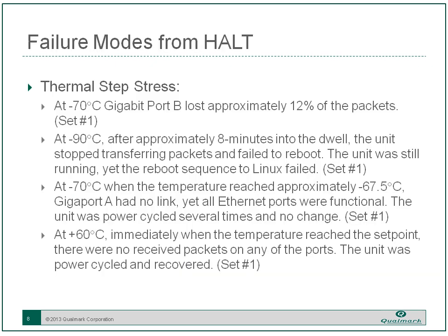Here are some examples of descriptions of failures found during a typical HALT. Simply recording just the stress level of the failure is not enough information. You'll want every detail of the failure mode to record when you move forward. You'll want to be as specific as possible, as the examples listed here are. Information pertaining to what test and specific stress the failure occurred at, how the product failed, what data functional test equipment may have gathered, and any other visual observations that were made are all very important. They are key components for performing root cause and corrective action, as well as guiding that functional test development for HASS.